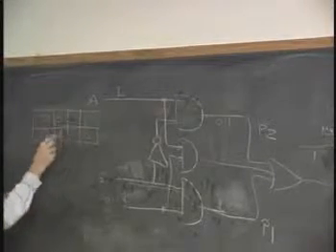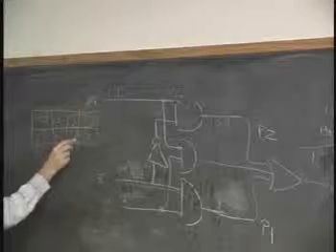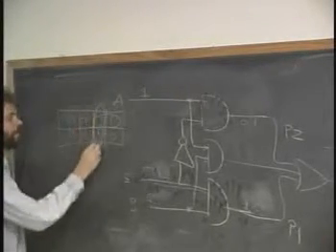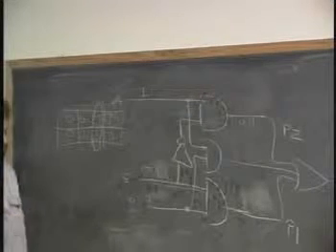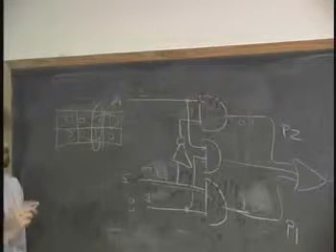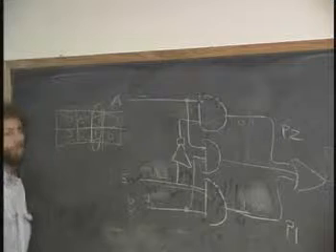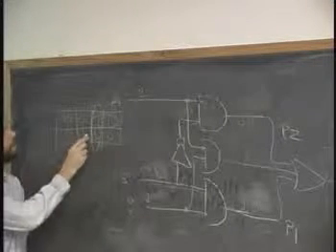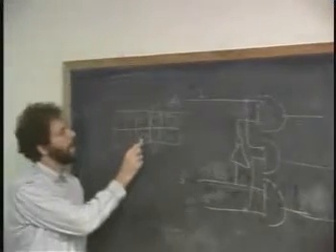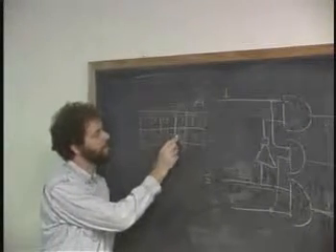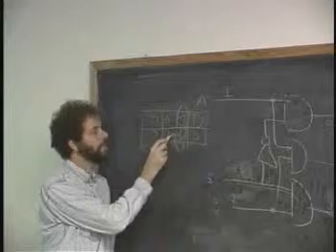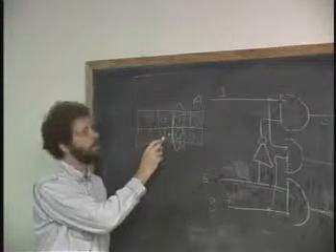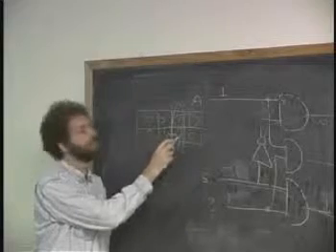Like so. I used to go like this, I used to go like this, and now I'm going to put in another one that looks like this. You remember the rule of the Kmap was that if I change one input, I move across one boundary. And what I'm saying here is that if the output is high and one input changes, I move across this boundary, but I stay within the confines of an AND gate that is not sensitive to the change.